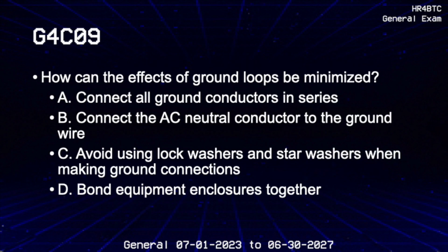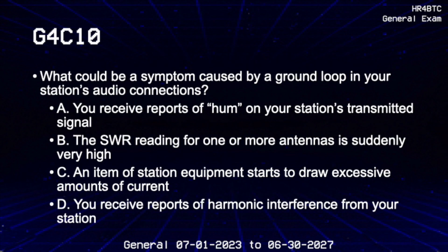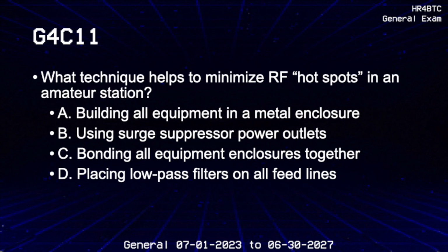How can the effects of ground loops be minimized? Bond equipment enclosures together. What could be a symptom caused by a ground loop in your station's audio connections? You receive reports of hum on your station's transmitted signal. What technique helps to minimize RF hot spots in an amateur station? Bonding all equipment enclosures together.